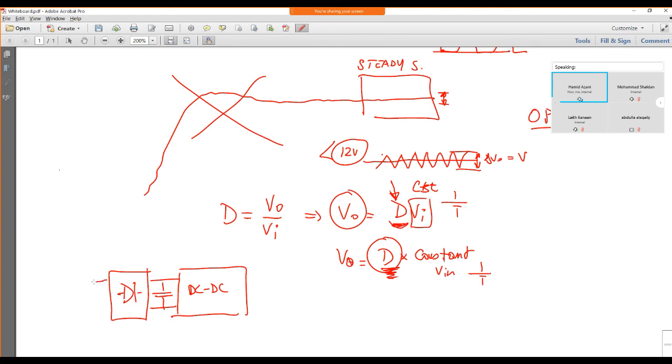The whole circuit will be connected to a socket, which is a single phase AC socket. So this rectifier will take that AC and rectify it, and this capacitor will make it a little bit smooth, like a DC. So that DC will be given to our DC to DC converter, and there we can adjust that value. You can increase it, decrease it, and so on, to satisfy our load.